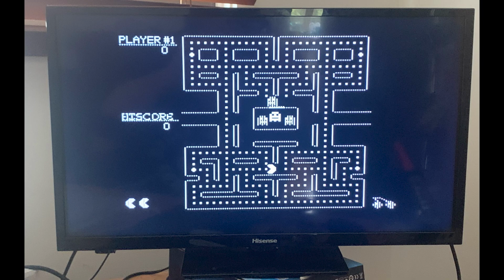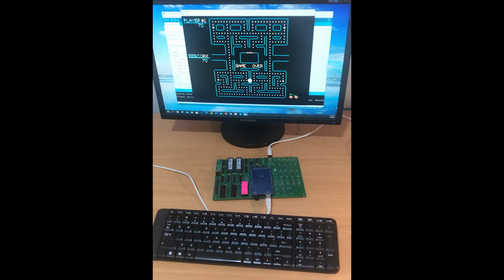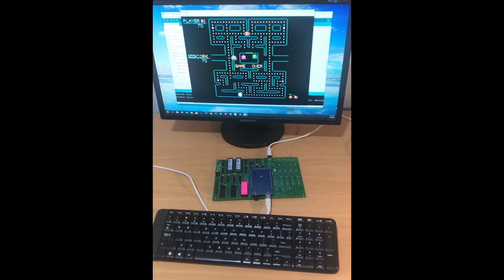Now this image is stored in EPROM, but I really want to be able to access images stored in RAM. Then we can actually play the game. More specifically, I want the 6502 CPU and the raster generator to share some memory. One way to do this would be to use dual-ported RAM, but I really don't want to go down that pathway.